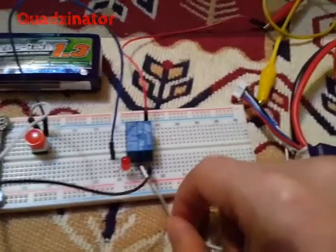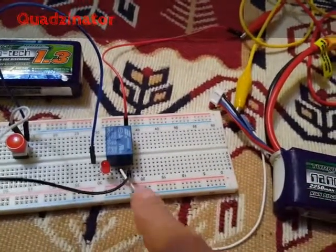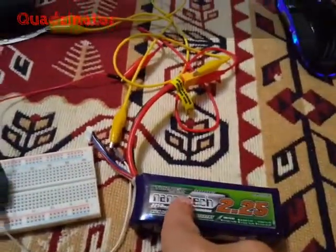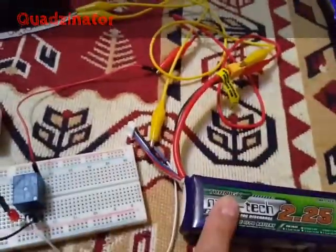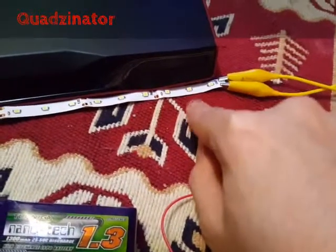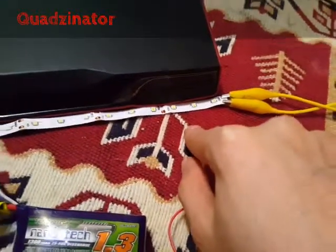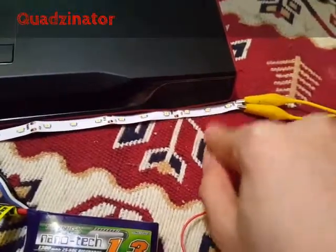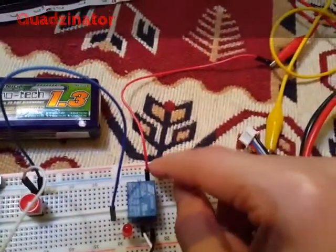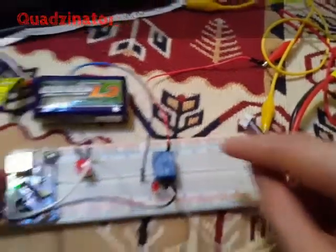And the high voltage circuit is connected from the third pin in the middle to this battery, which is 11 or 12 volts approximately, which will light up this LED strip that only operates on 12 volt, and ends up in this fourth pin right here.